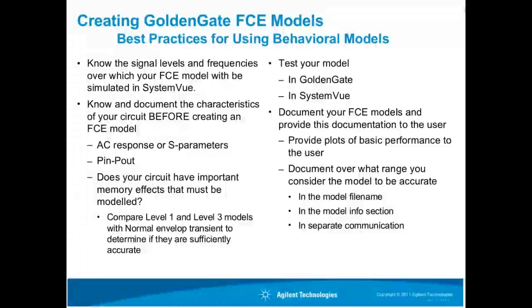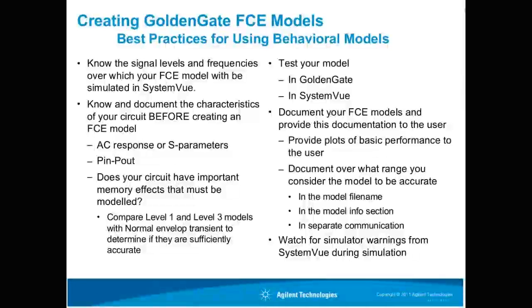And while you're simulating in SystemVue, you're going to want to watch for the warnings. If it's going above the top amplitude level that you've modeled your circuit to, you're going to start to get warnings, and you're going to want to catch those.